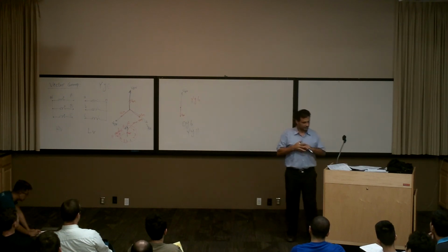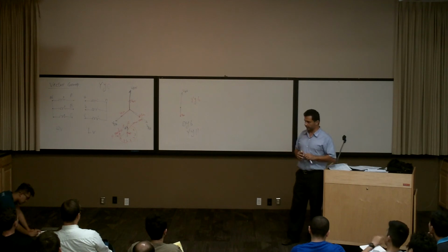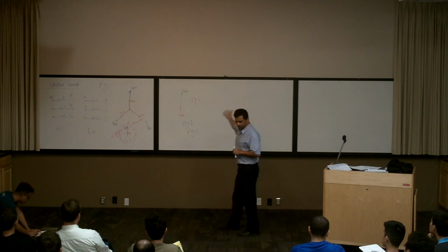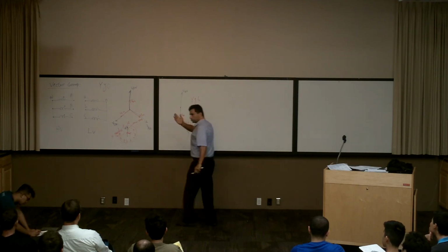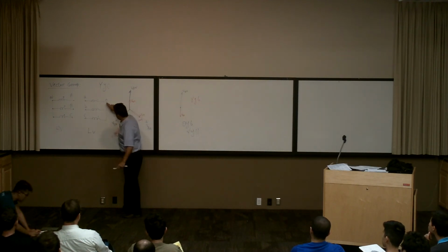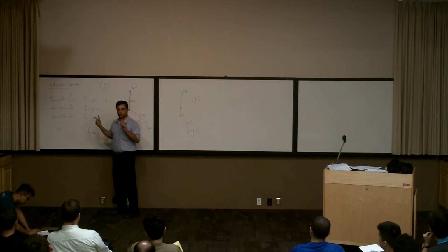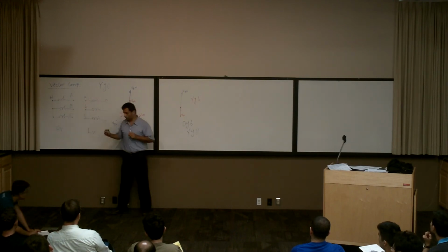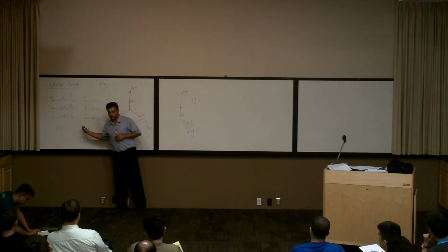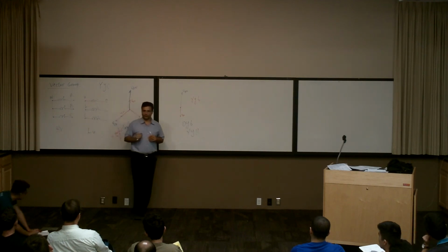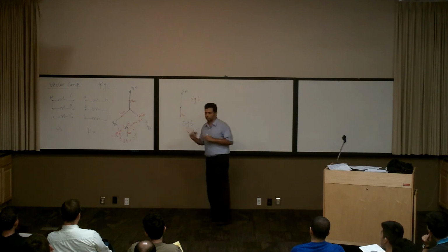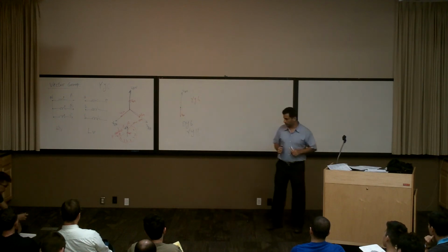These are the easy ones. I just wanted you to get a feeling of how it works when we say 11, 1, 2, 3, something like that, and how these numbers come up. For the Y-Y connection, there are only two cases, either 0 or 6. There's nothing else. You go check it. Put the dots somewhere and check what the group connection is. It's going to be one of these two. Practice it and find it out.